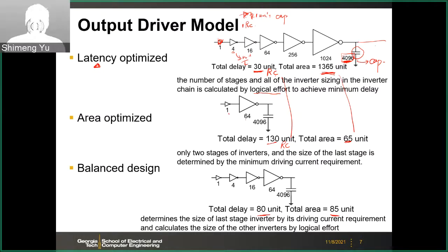So you may have different designs depending on your optimization goals, or the metrics, or the specification of your memory. In general, for SRAM cache design, you want to optimize for the latency. DRAM also you want some latency optimization. But for other long-term memory and flash, then you may consider more on the area.